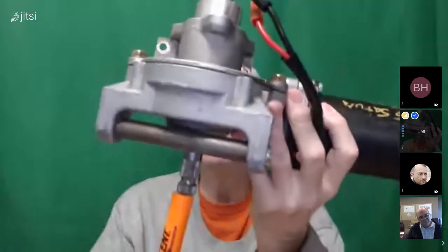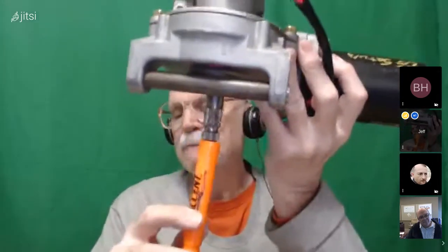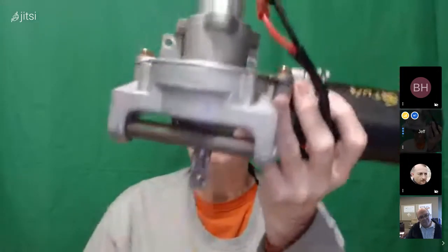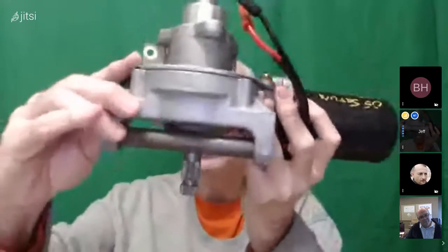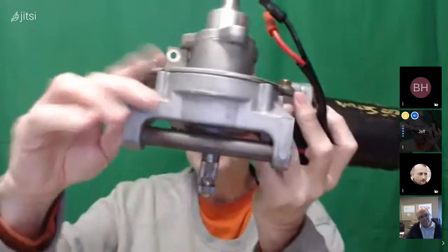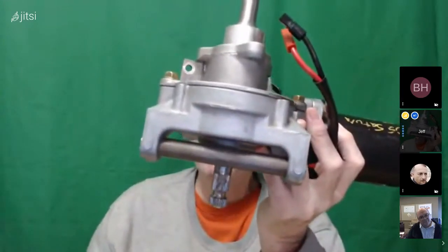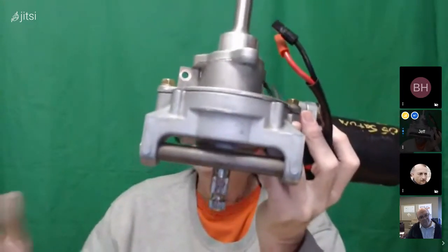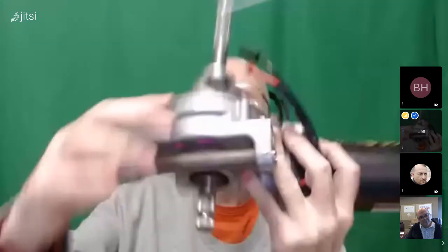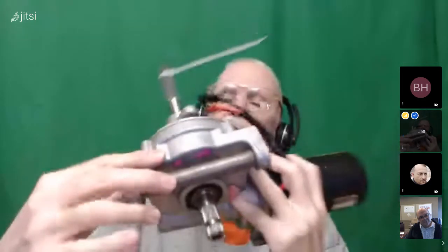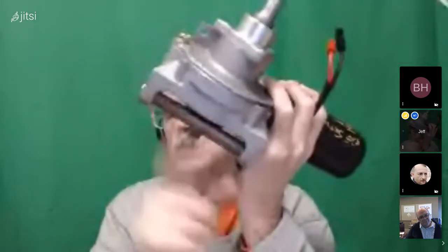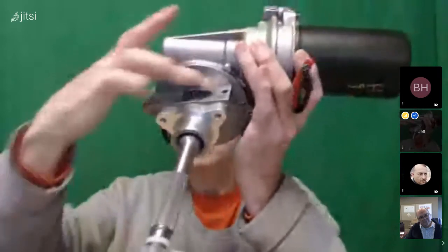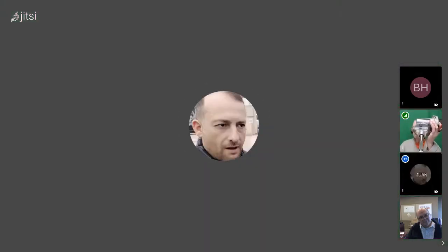But then I still have the problem that once I've got this motor mounted up on top, and here's my steering shaft, and I've got those tied together with some kind of a coupler there, I still have to physically mount this motor. And I saw on Juan's lawn tractor, he had some kind of a steel bracket that came up over, so I assume he bolted it on either to the frame or the side of the housing, because you've got these holes in the top to hook onto, and you've got this big thing across here you put a bolt through, and then where I took the controller off,